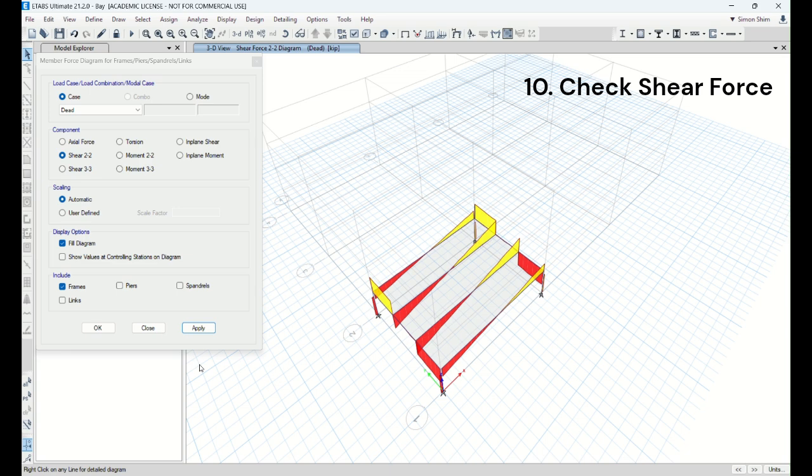ETABS, right? Calculate the self-weight. We're going to assign the uniform live load 100 PSF. They calculate the tributary width and load it along this beam, right? They calculate shear force and bending moment. So this is a 3D example I will send you, but I want you to do the exercise from scratch this much. If you know a few exercises, it's easy to draw the 3D.